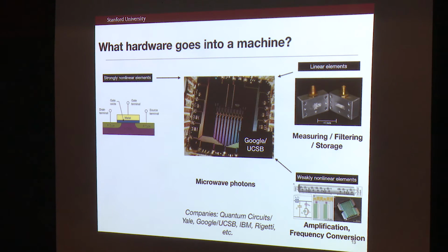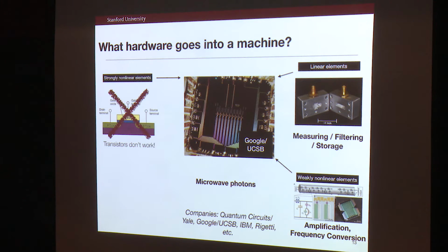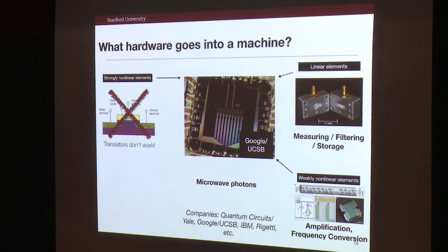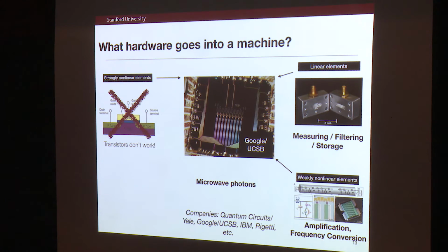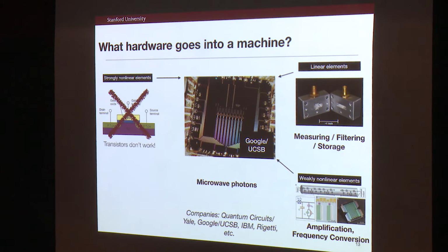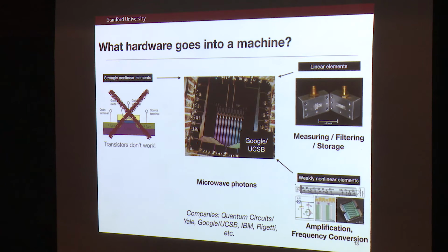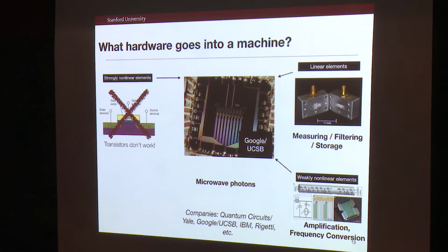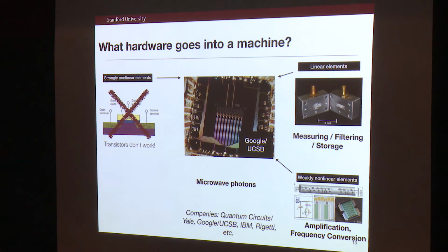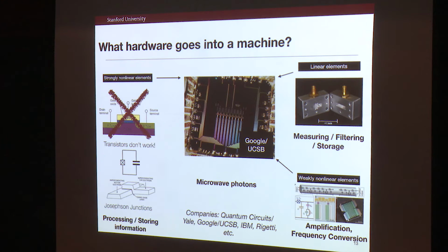And the important thing is, so this is a transistor. If you're processing quantum information, you can't use transistors for your microwave frequency photons to generate interaction. And that's because the way transistors work, your electrons go from one side to another through a diffusion current. So that means they're bouncing around and generating a lot of noise, and they're telling the world where they are and what direction they're going. So there's a lot of decoherence. These types of devices don't preserve coherence.